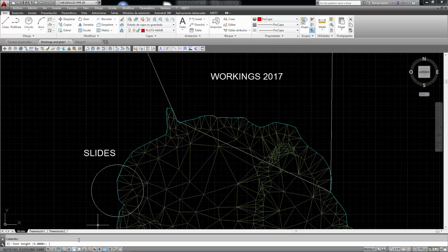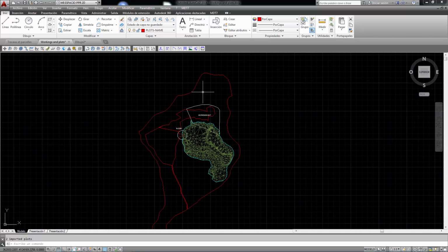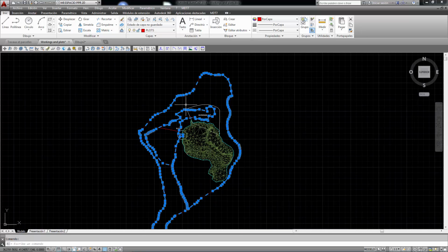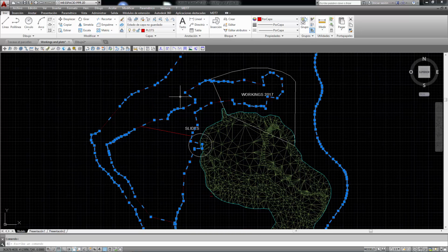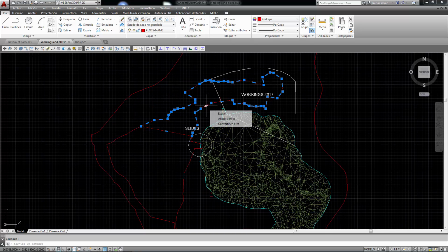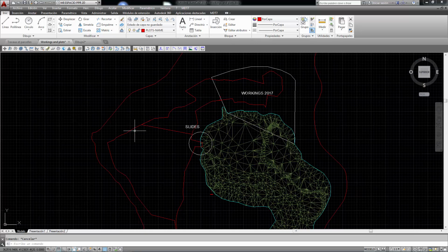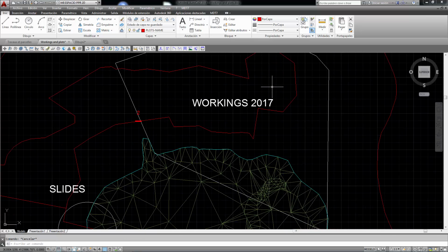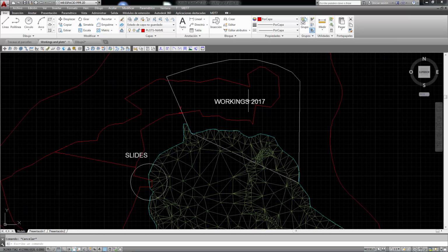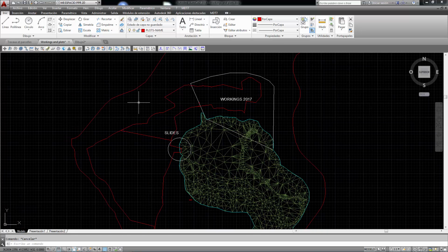So to do this, we go to MDT plots, import GML, and import the plot ending in Q and the plot ending in P. We accept, specify a text height of 5, and here it is. As we can see, this plot refers to the exploitation of the quarry, whereas this interior area is beyond that, to determine the occupation of the work plan, not to buy it, but to exchange it for another plot we are going to create, the same size in square meters, and adjoining this plot.